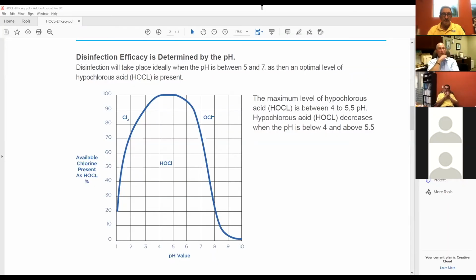So there's the pH curve for chlorine, and you can see when you're at a pH of 10 plus, everything you have is hypochlorite. That's what comes out of bleach. So the pool bleach that you're using and injecting to a pool, everything is hypochlorite. As you reduce the pH, the amount of HOCl, which is hypochlorous acid, increases. And when you get to a pH of 7.5, which we all know in the pool industry, you have 50% hypochlorous acid and 50% hypochlorite, standard teaching in a CPO class.